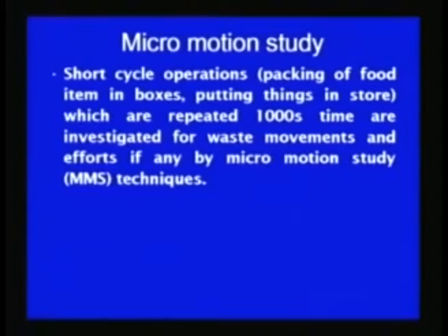Among the techniques which are based on film, one of them is the micro motion study technique. This technique is mainly used for short cycled operations which are repeated thousands of times in a day, and these are carried out very quickly, say, packing of food items in boxes, or putting things in a store.